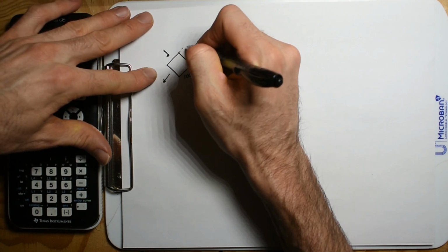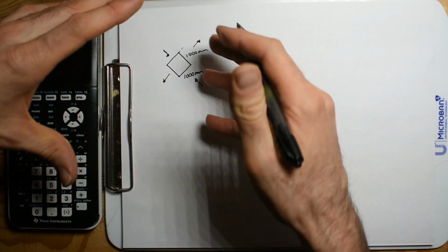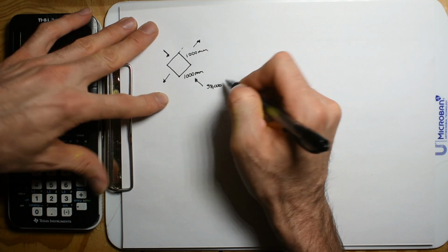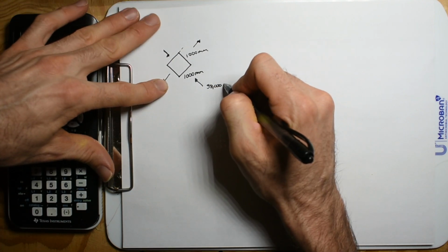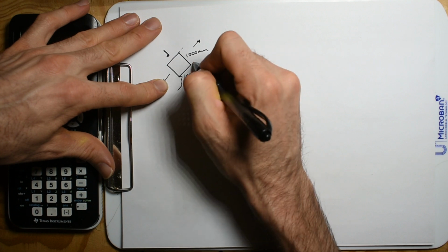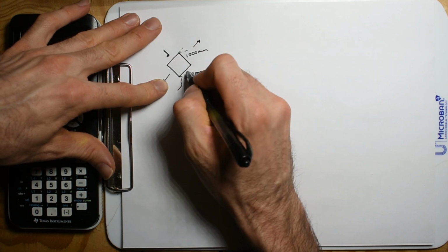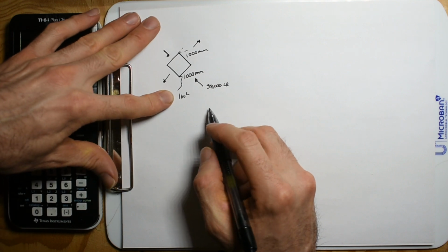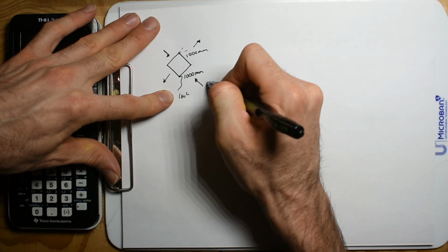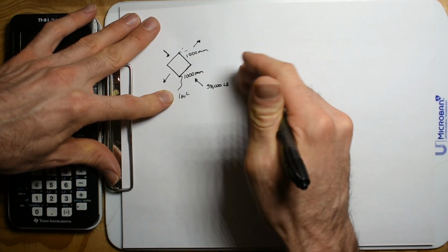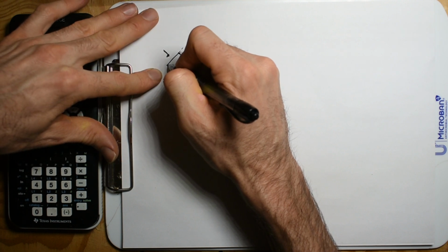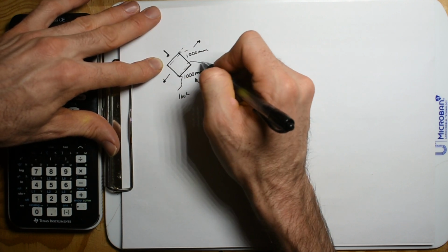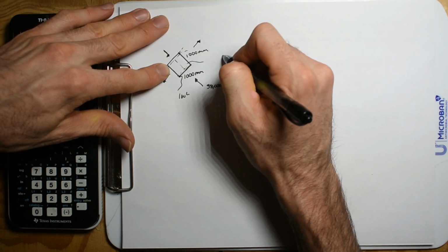And so let's say this is just a 1-inch cube block, and let's say we put that 58,000. I always like to use numbers that I'm familiar with, but we got 58,000 pounds. If this is a 3-dimensional block, we got a surface area of 1 inch squared. And when we put this 58,000, that's the max that steel can do. So it's going to change in length this direction.